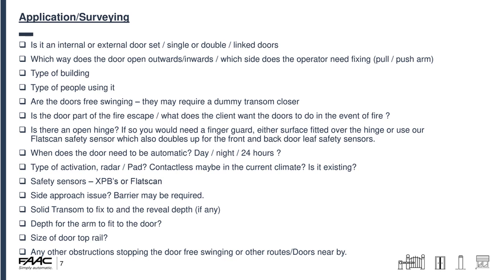Is the door part of the fire escape? What does the client want the door to do in the event of fire? Very important. Do they want the power to cut and it just become a manual door? Do they want the automated system to carry on working after the fire alarm has gone off? If that is the case, you'll need an uninterrupted power supply to the operator.